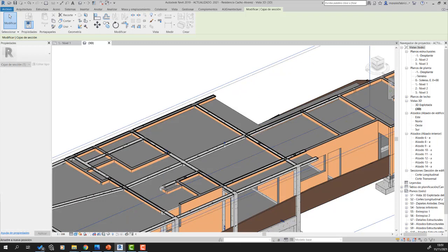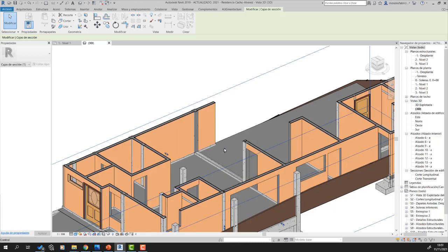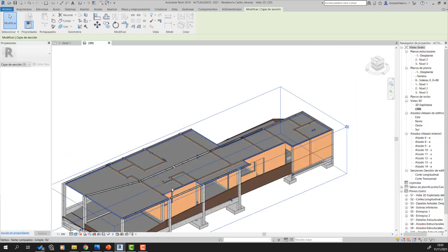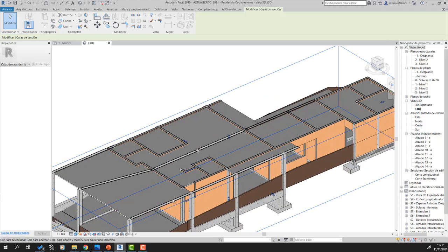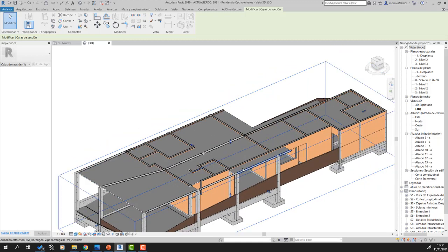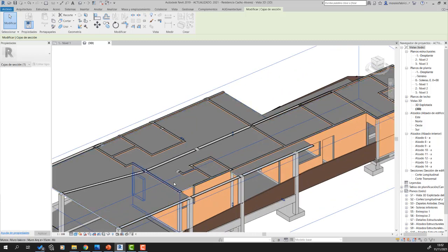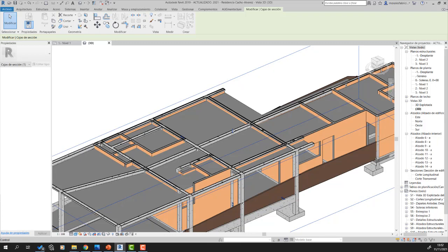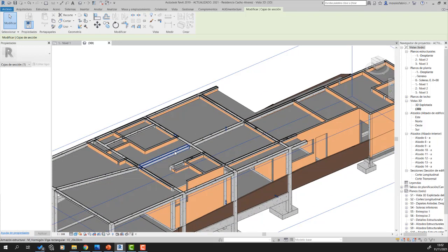And as we go up, we reach the ceiling. The ceiling is not a structural component, but it is shown here in this very basic beam model just to show you the different parts or anatomy that a house normally has. This region here is the stairs to go from the first floor to the second floor, and as we continue to go up, now we can see the beams. These beams have the functionality to transfer loads from the story deck to the columns, and that's the main objective of all of these reinforced concrete beams.